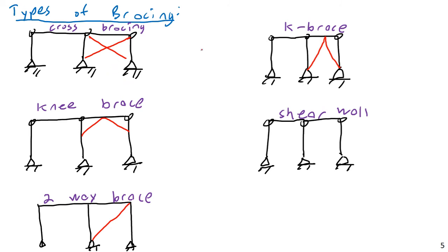When you have load applied in the other direction, the other member will carry the load and tension. In the two-way brace, however, the same member does double duty. So that means you can't get away with using a very light member. You have to use something that has a substantial buckling resistance. So you're not going to be using something like an angle iron. You definitely can't use something like a cable like you can on some light one-way braces.